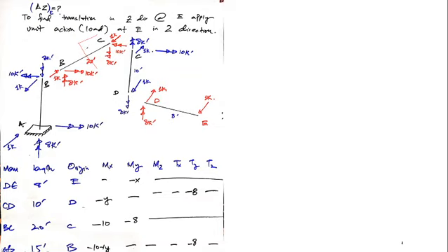Origin is C, yes. And obviously this is Z. I have to find all moments here. This 10 kip-foot would be balanced with 10 kip-foot. This is clockwise, so I'll apply a counterclockwise 10 kip-foot. This 8 kip-foot is moment in Y direction. It would be balanced with upward 8 kip-foot. That would be a counterclockwise.